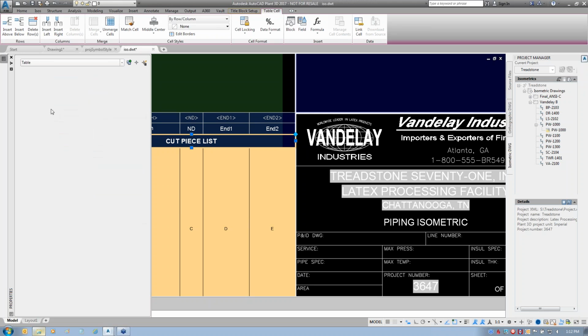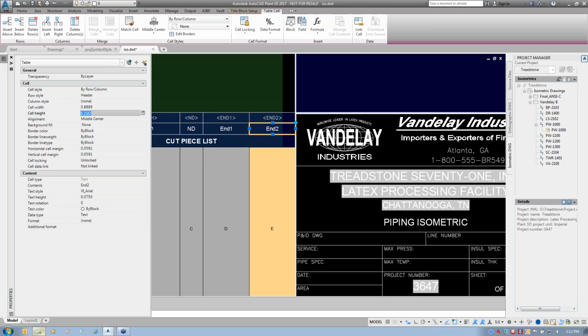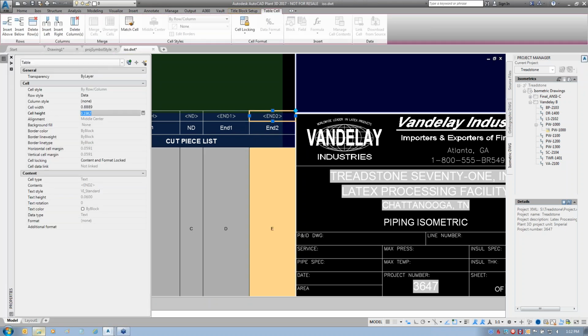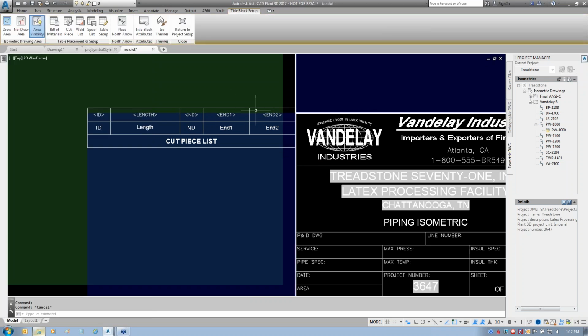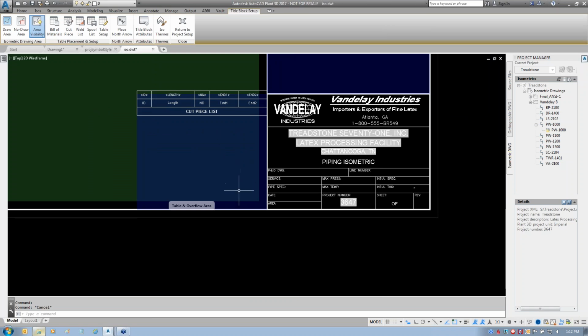This one I can set in the cells here, and it will remember it from then on. So we'll set those to 1/4 inch. I'm controlling all my formatting so it will look the way I want it to look. Even though that put it up there, that's okay. It still understands this is the draw area. It just does that automatically, and that will keep those lined up.